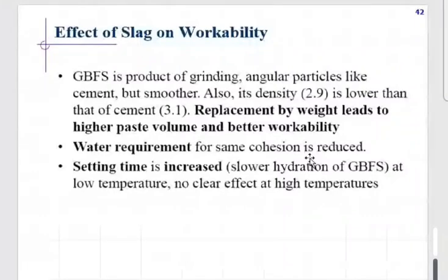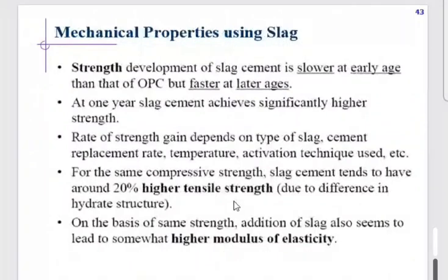Clear? With respect to workability, if you increase this amount, you can have better workability. This better workability comes from its low heat of hydration, because it lowers the heat of hydration and setting time, so you can have improved workability, or better temperature effect as well. This is the best thing about the slag. So once you are recommending mass concrete, heavy concrete, where a lot of volume of concrete is there, you can also recommend that slag should be used.